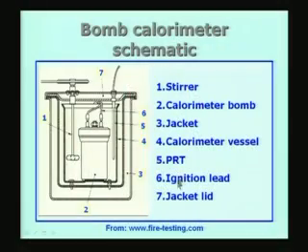Okay. So, the ignition is done by the leads shown here, and inside there is a wire. There will be a wire inside. I have not shown it here, but there is a wire. This wire is in intimate contact with the fuel pellet, whose calorific value or heating value I want to determine, and a suitable power supply is used to start the combustion process.